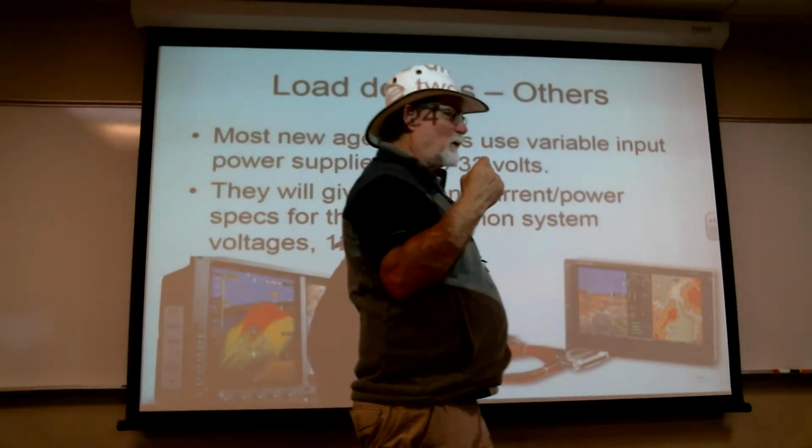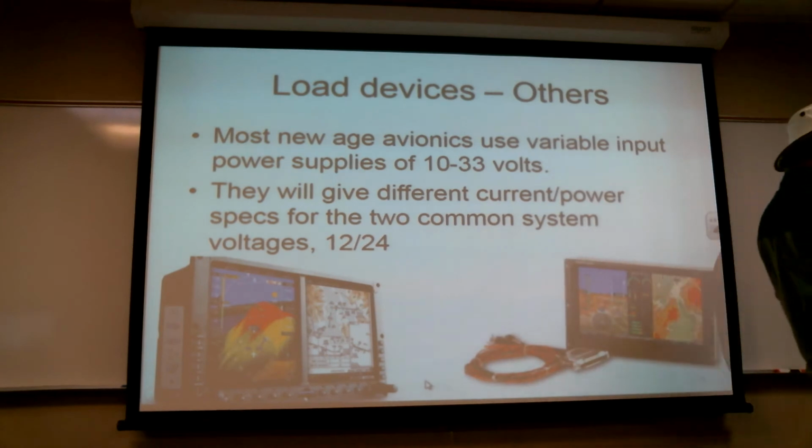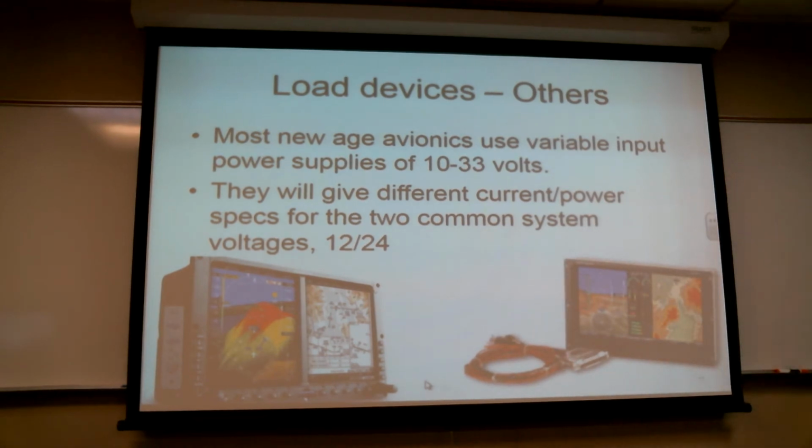And in fact, the way they've got it configured is there's a little plate that goes over it. On one side, it says 30 volts, and that's screwed in place, forcing the switch into one position. If you unscrew that little plate, turn it over, move the switch, put it back in, it then kicks it down to 15 volts. They put that extra plate in there just so somebody doesn't accidentally bump the darn thing.